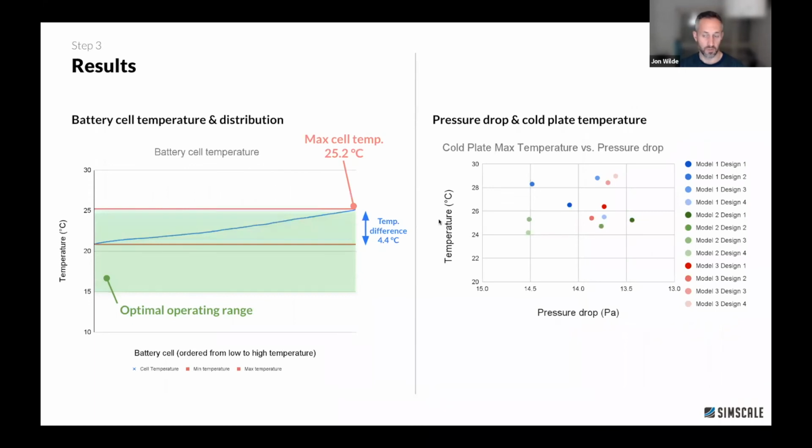And then you can plot them all. So you end up with something like this on the right. Normally you have hundreds of these dots with all of the lines between, like the pump that we looked at at the top before. And yeah, you can say, okay, I want to optimize for pressure, like which one should I pick, or temperature, or like I said before, cost or weight, or whatever the main kind of design criteria is. You can figure out what design you need to choose.